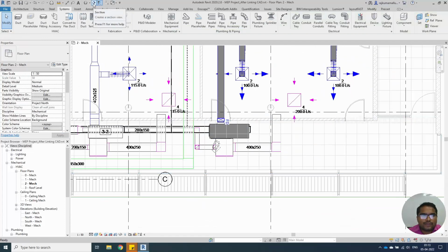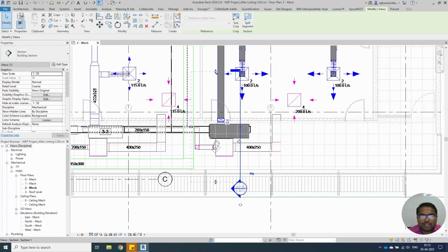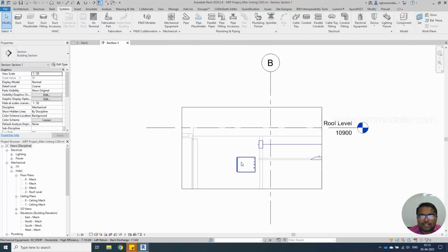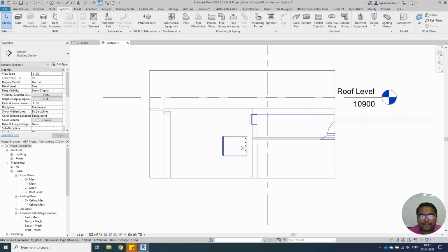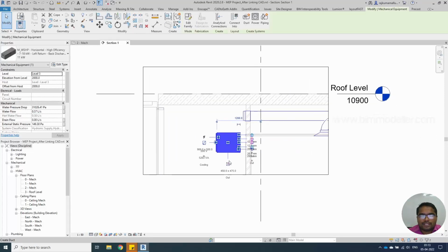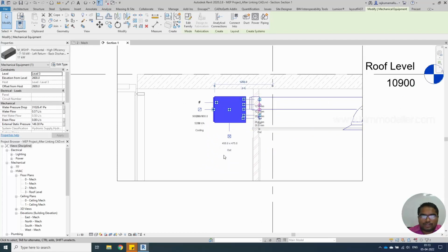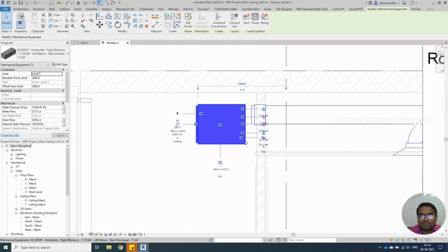You can take the section view from here. You will be able to create this section view across the equipment and the ductworks to see the height. Double click on the head and you will be able to see them in the section view. Make sure you're using fine to see the elements clearly, and you click the equipment, and if you need, you can align those right to the element like this. I recommend you to align this at a later time for coordination purposes.